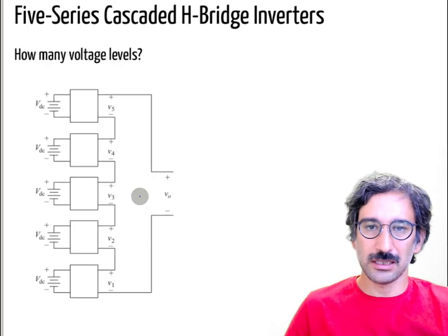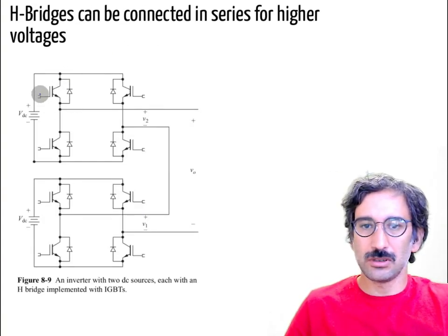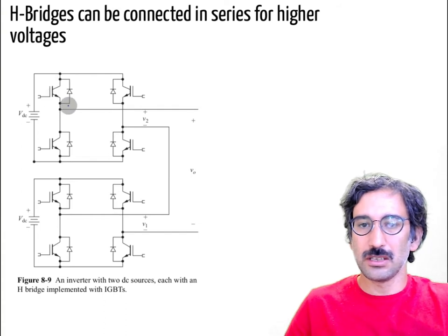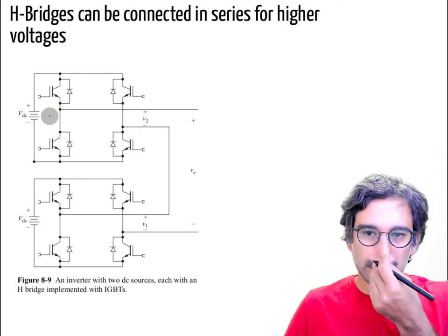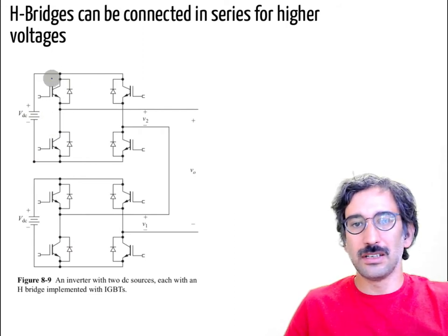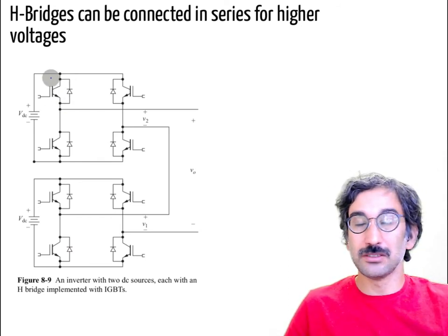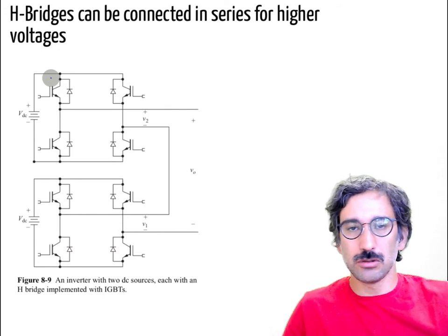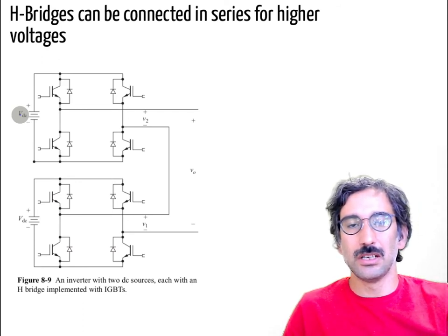And the nice thing about that, again, it doesn't have to be photovoltaic panels, but that converter, or that switch, just sees a voltage level with respect to that VDC voltage level. So for example, if you have a switch that can withstand 1200 volts, maybe your DC link voltage is at 1000 volts, so you are using barely enough voltage switches.